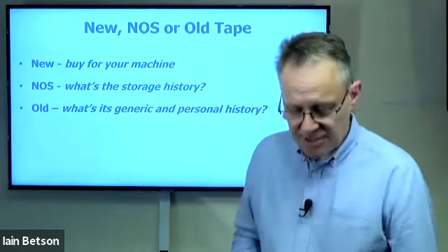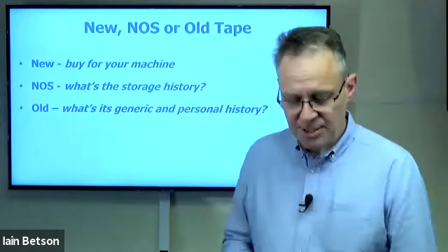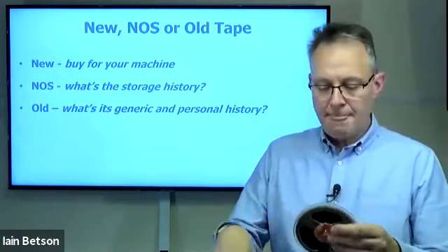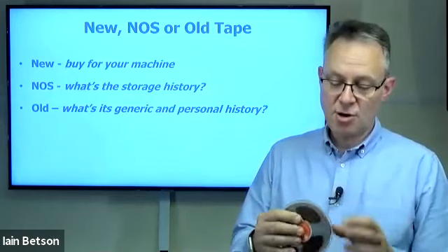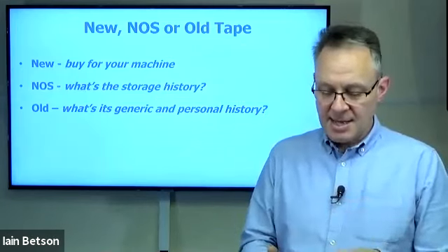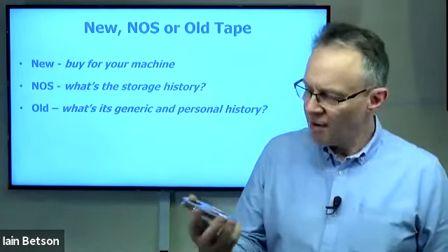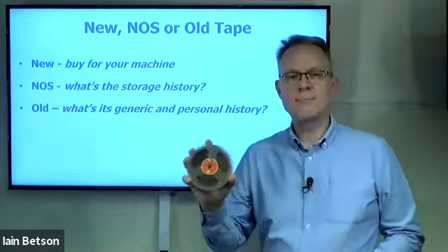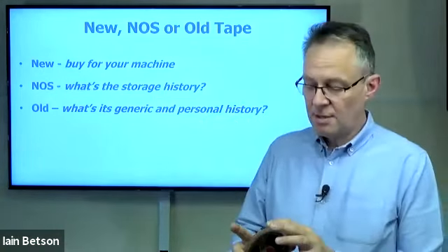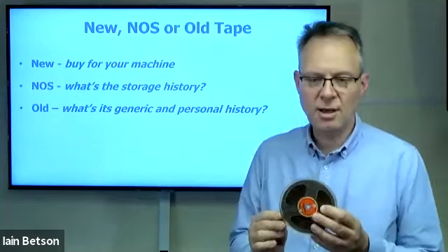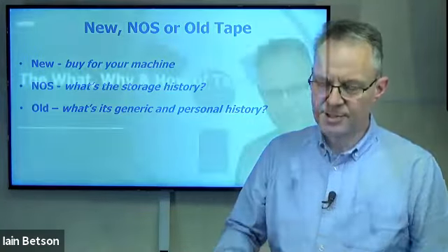You'll find other tapes such as this particular Philips reel of tape, again not back coated. I would use this to demonstrate a thing later on called sticky shed syndrome and what you should look out for. But again, you can tell it's very oxidey, very thin, domestic grade. Nothing against that if you're using tape in your home listening. But again, I would caution about using this for any professional use.